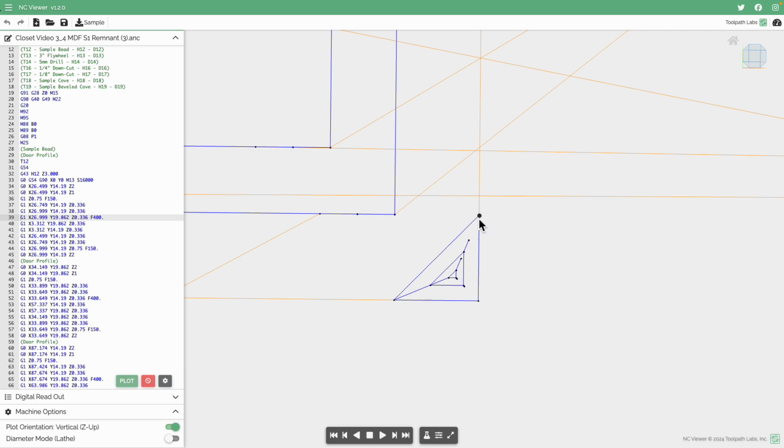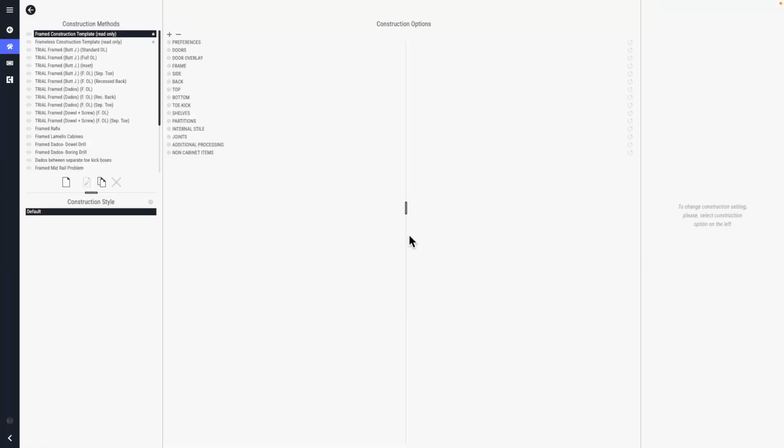Now, the actual bead itself on the outside radius would be that radius we set. But if we're also trying to corner clean the inside radius, we can do that too by adding yet another 1/8 inch downcut pass at the appropriate depth and appropriate corner radius. Now, as I mentioned before, this is also relevant for pretty much any other pocket operations associated with any connection, like rabbets, dados, and even box joints, which have some pocket operations.